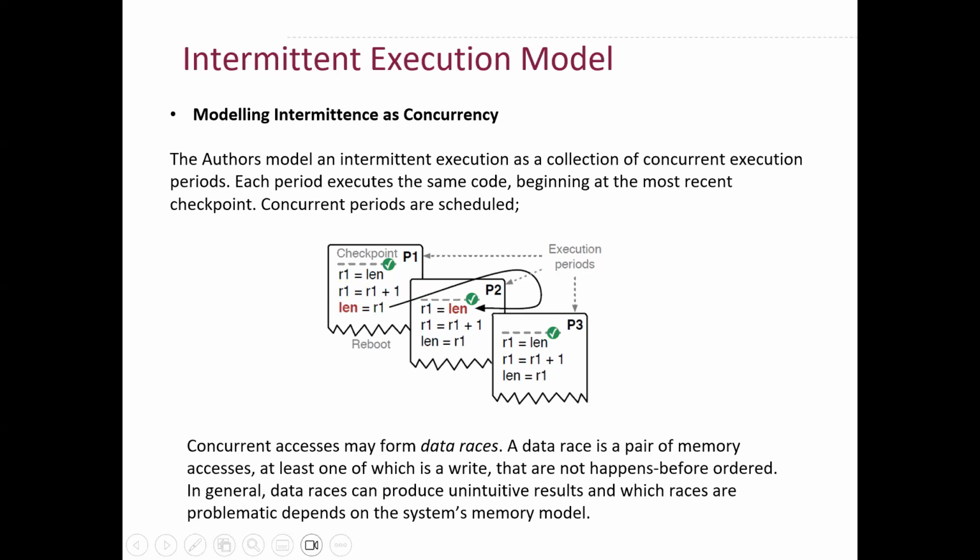This is something which is impossible in continuous execution. And racing accesses to non-volatile memory in intermittent execution can be problematic, because a race leads to an unintuitive result. If a preempted execution period modifies a non-volatile memory location, then a preempting execution period reads the same location, and the preempting period's read precedes all of its writes to the location. So this race problem can be addressed by DINO's architecture, or DINO's programming paradigm.